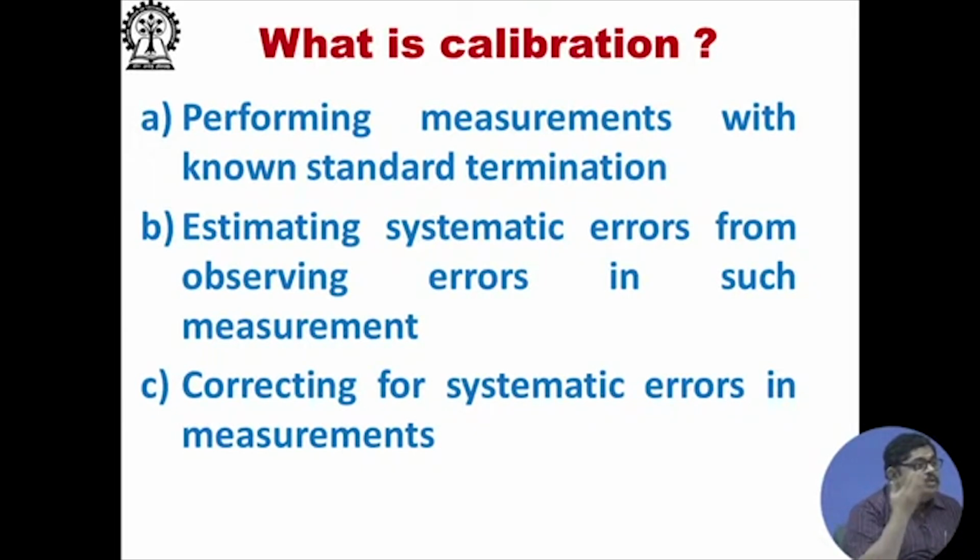That means, now when you take the actual measurement, you will remember that these are the errors. So, you can do error correction. This whole process is called calibration. The network analyzer does this calibration.